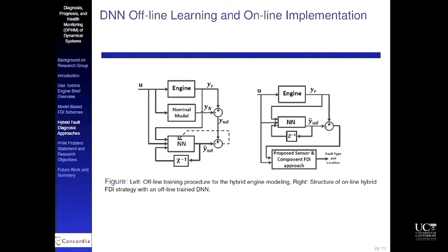The conventional thing is to design your neural network to capture the dynamics of the process, so that the dynamics of the process are implicitly represented in the neural network. This is not what we are doing. We are doing something completely orthogonal, or dual, to that. We want this neural network to function as representing the unmodeled dynamics.